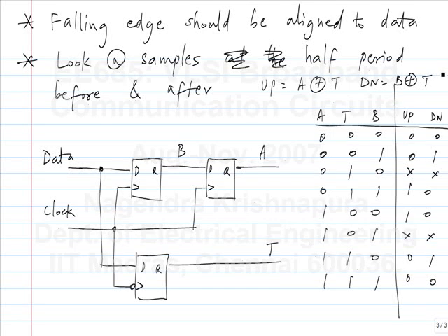It's a simpler realization, but you can realize the whole thing. That's not a big issue. If you are working at extremely high speeds and you want to simplify the circuit implementation as far as possible, you can simplify the truth table a little bit like this. Also note that if both up and down are 1, then it's not contributing to the phase advancement or receding of the VCO.